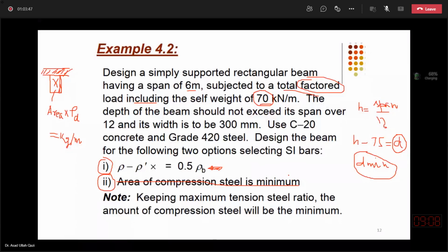So if it is a simply supported beam, I have no concern about serviceability. So the architect depth restriction fulfills directly or indirectly the serviceability, but I am a little concerned about the minimum required for the singly beam. So I need to check that in the solution of the problem.